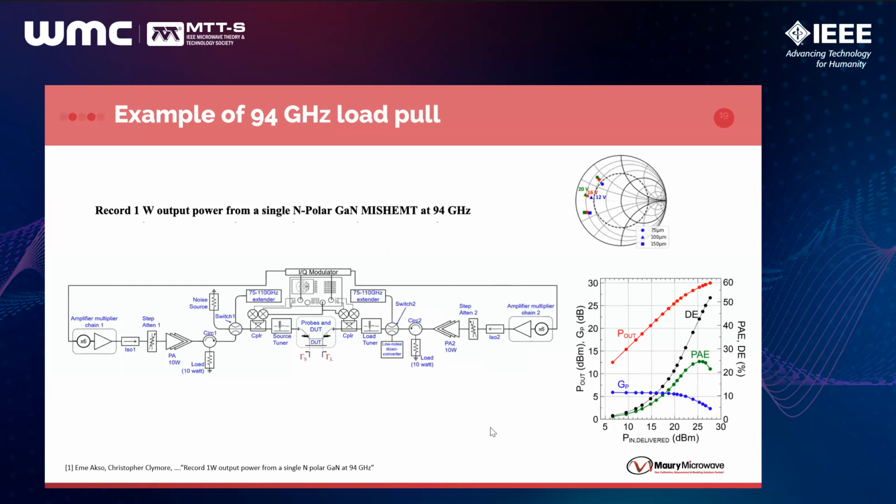Nowadays, we also see a lot of requests for very high frequency measurements, and there are solutions. And as you can see, the device characterization setups get more and more complicated, more and more important. In this case, we are using a VNA with frequency extenders in a waveguide setup, and using an IQ modulator to generate the signal, multiplying the frequency of the signal to go to the RF frequency required. We have step attenuators to sweep the power.